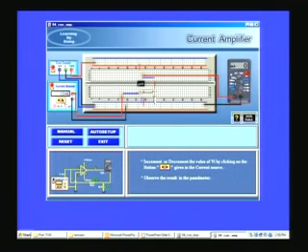Let us give milliamperes. Now I give 1 milliampere and the output current is 10 milliamperes. If I now go to 2 milliamperes, it is 20 milliamperes, 3 milliamperes means 30 milliamperes. So you can see the output current is increasing nearly 10 times, which is given by 1 plus R2 by R1 approximately. So this is an example of a current amplifier constructed with the op amp.